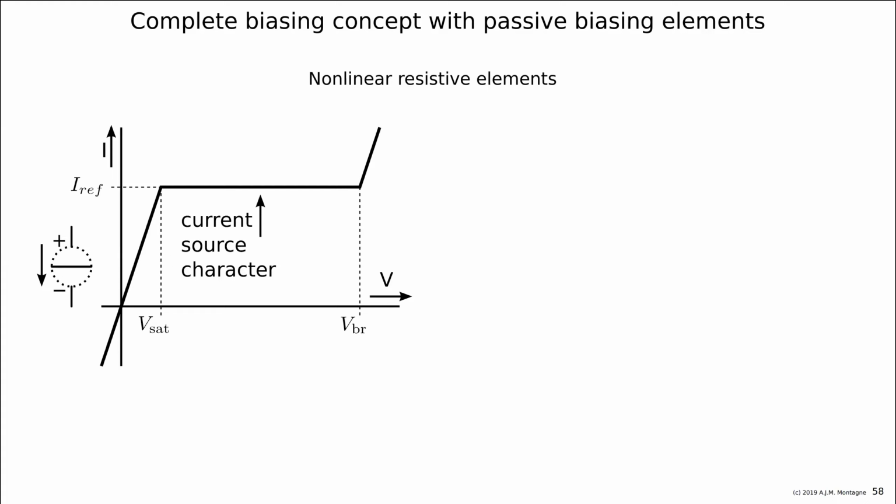We cannot use this current source for all voltages across it, as we can if we put ideal current sources in there. But no, not if we do a practical one. And everyone probably knows the saturation of a bipolar transistor and the linear region of a FET, in which we have this kind of resistive behavior for low voltages and low currents.